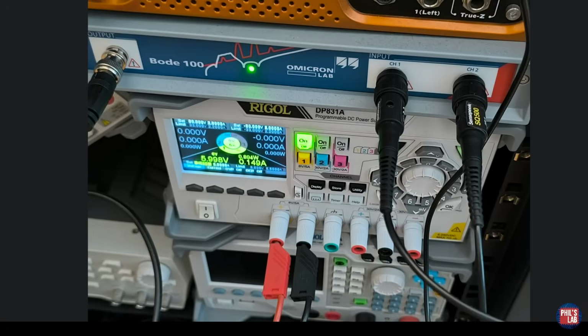Now let's move over to performing real-world measurements in the frequency domain to try and measure the power supply rejection ratio of our LDO regulator. For this, initially, I'm going to show you how to do this with the Bode 100 vector network analyzer, as pictured on the top of this image, where the output of the Bode 100 feeds our line injector's AC input signal, so that will apply this AC signal bias. Then the channel 1 input of the Bode 100 will connect to the input of the LDO regulator, and channel 2 will be connected to the output of the LDO regulator.